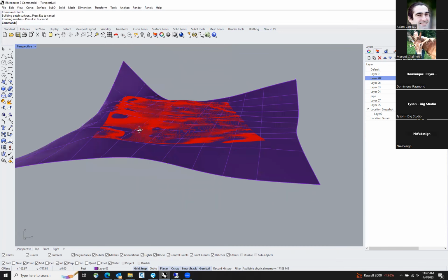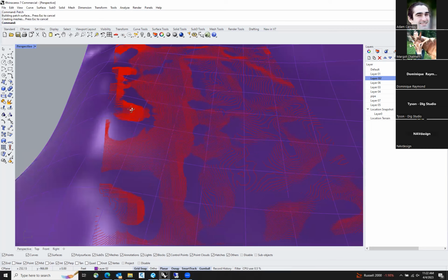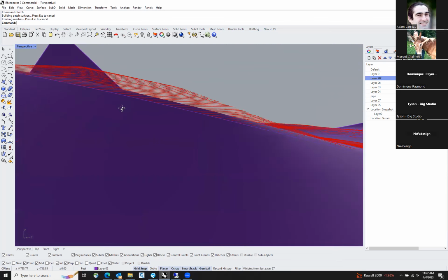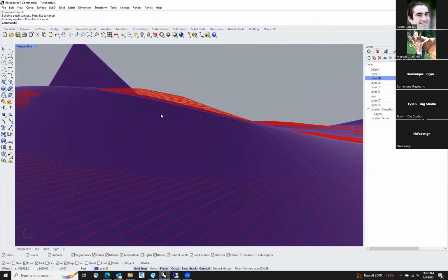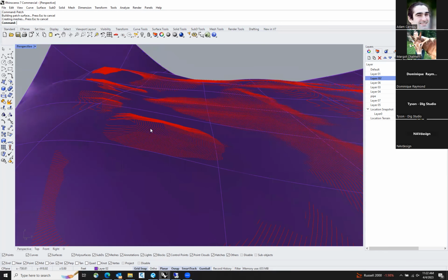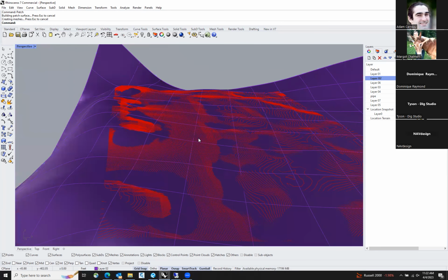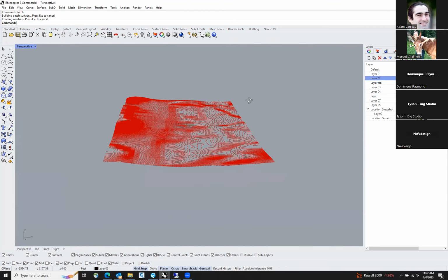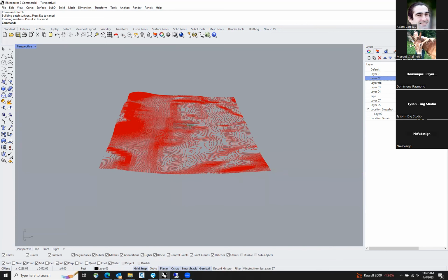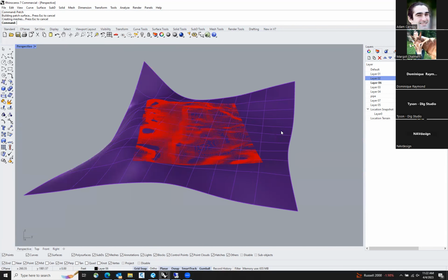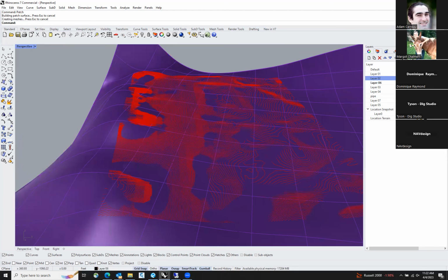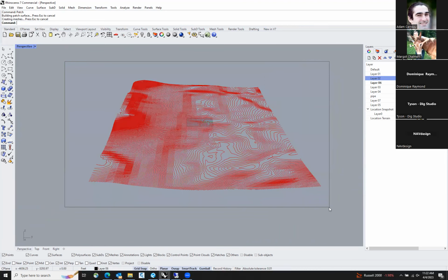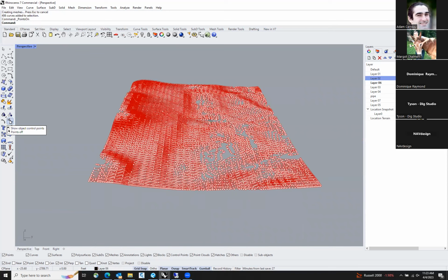As you can see, it patched that surface to those polylines. But you can notice that it's not 100% accurate because it's interpolating that surface based on those lines. So it's not 100% accurate as a surface. I'm going to go ahead and turn that off. So you can see the 10 grid lines in either direction. Another way to do it to get a little bit more accuracy is to select it all, show your points.